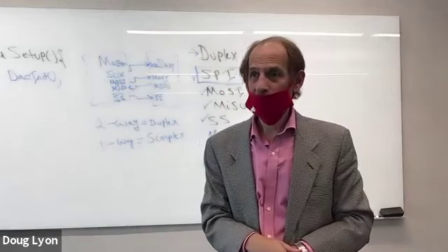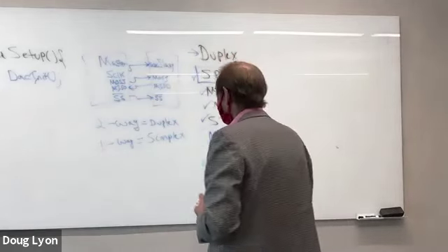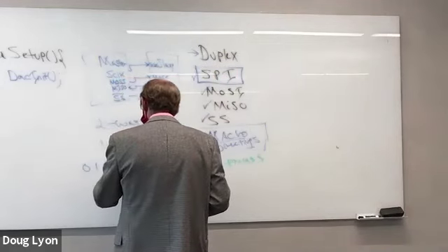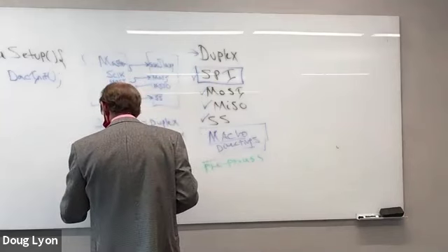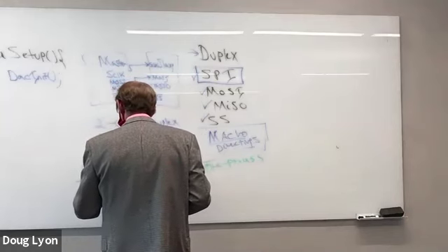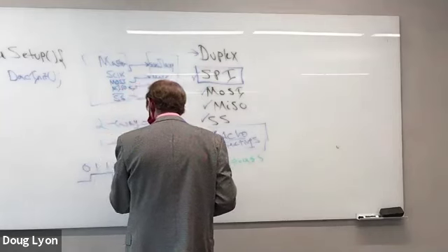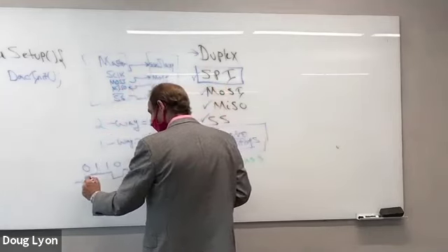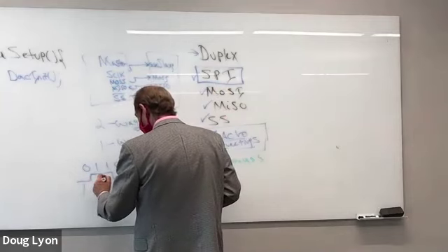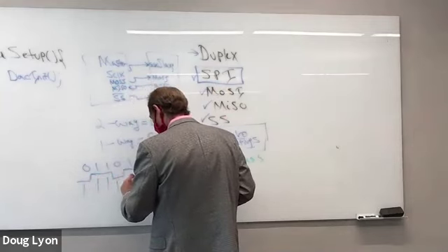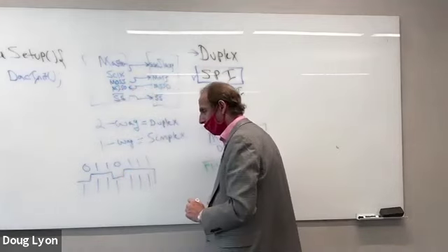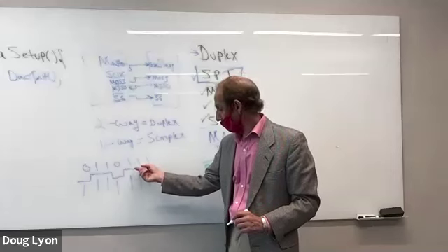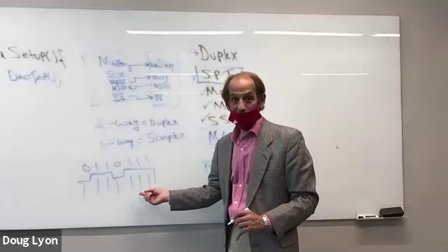Zero translated into bits. Well, there's bits going back and forth, no doubt. But what we want to know, 0110111, is when the 0 begins and when the 1 ends. How do I know that this is 3 bits? And the answer has to be because of timing. So if I have sample timing, right, from a regular interval clock, then I can know when to sample the input, when to measure the voltage, and figure out what the value is.